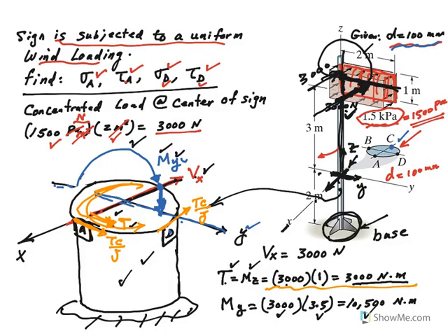Now, we also have the transverse shear here due to this V sub x, right? So what would be the effect of this? Let me erase some of this stuff here so I can show you exactly what's going on. You just saw that due to this torque we have the TC over J here and TC over J. But what about due to this shear stress?